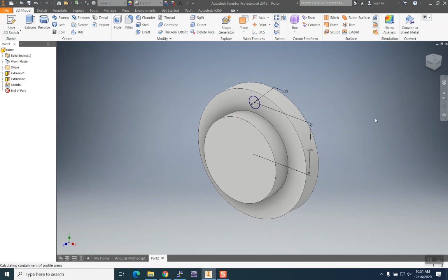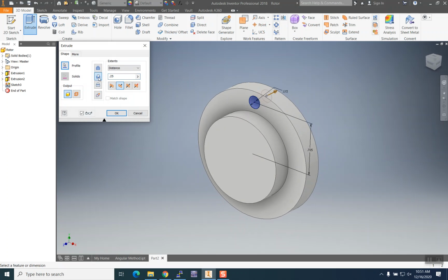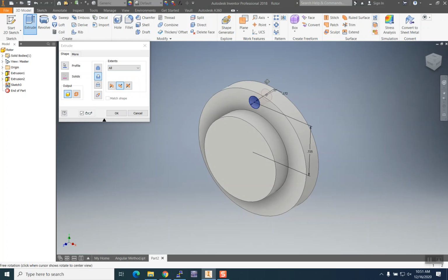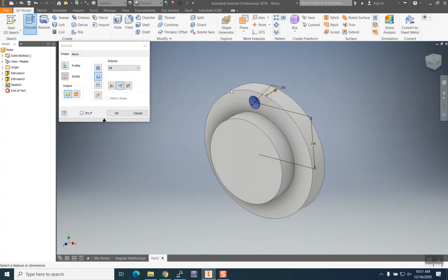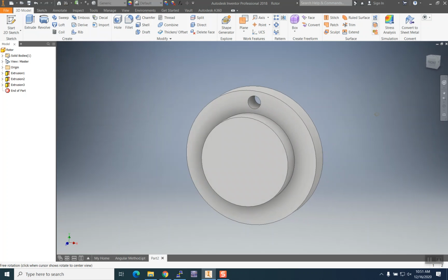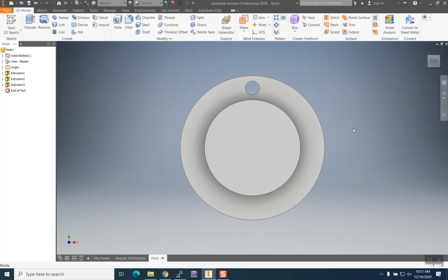I finish the sketch. I extrude that with the cut option. Do not use a distance whenever you have a through hole. Always use through all. It will automatically cut it through that larger of the cylinders. Now there's our hole. Now here's where our students get into trouble.